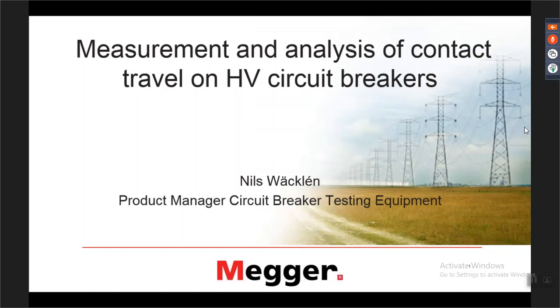I will explain all these parameters later. Arcing contact length in combination with dynamic contact resistance measurement, and we also have damping characteristics, which can be defined in different ways. And the problems that can be revealed with contact motion measurement.